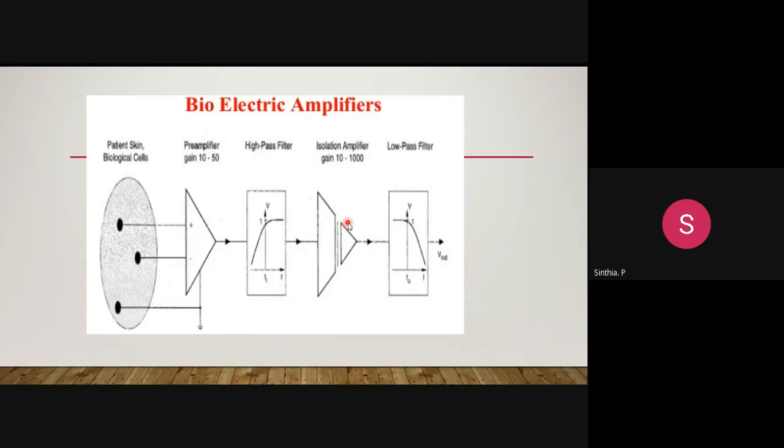Various principles are involved to realize this isolation stage. We will see either using a transformer or coupler to provide an isolation barrier. Digital isolation amplifiers use a voltage or frequency converter to digitize the signal before it is transmitted.